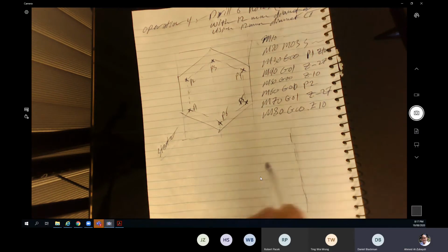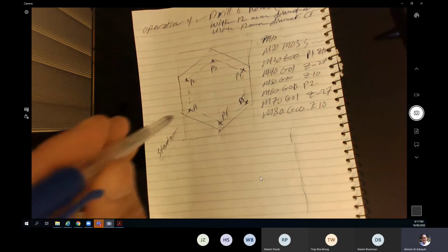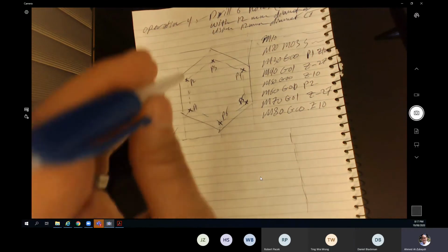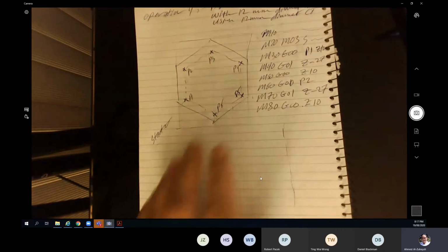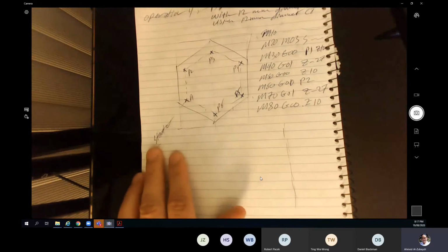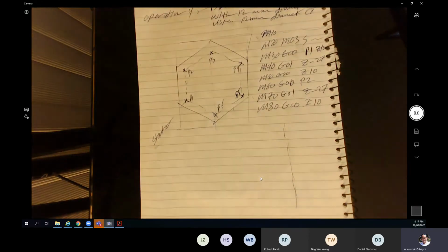So the only process we're going to make in drilling is, we go to the top of the work, we drill, we go up. Moving to the next one, we drill, we go up. Drill, go up, and so on. So just something like when we do the tapping, just doing the tapping during the movement. When we finish that, we travel to the start point and turn off the machine, because we will need to change the tool for the next operation with the 6 millimeter diameter cutting tool.